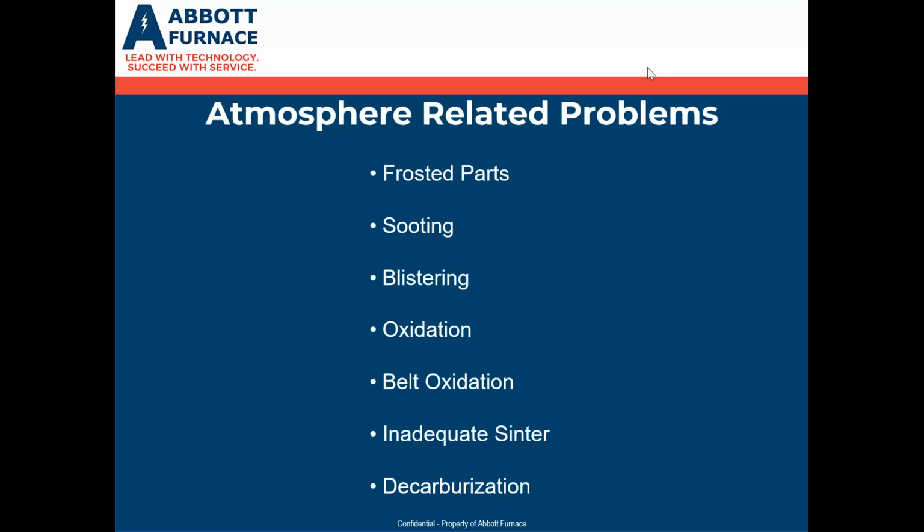When it goes from a liquid and hits a certain temperature, it becomes a gas. It almost erupts out of the interior of the part like a little volcano, and it causes blistering on the surface of the parts.